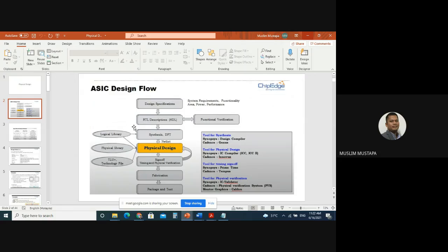So again, ASIC is application specific integrated circuit. This is an IC that is not reprogrammable. So once you load or create the circuitry, you are not able to change it anymore. But it's very efficient in terms of power, and if you do mass production it's going to be very cost effective compared to the programmable solution.